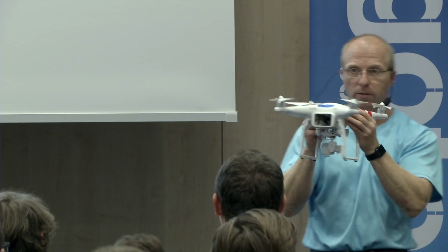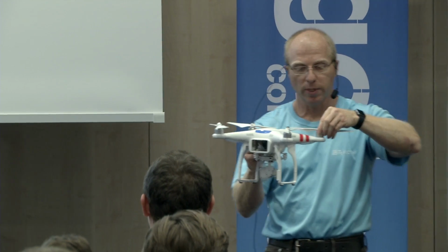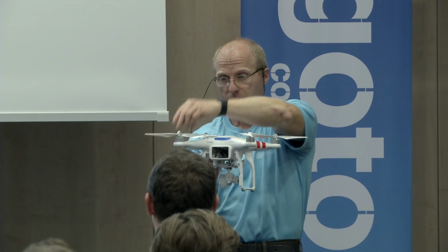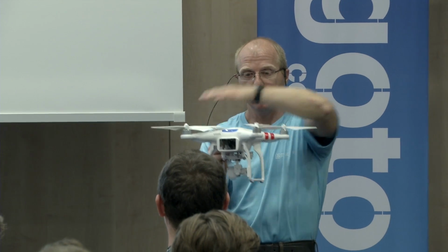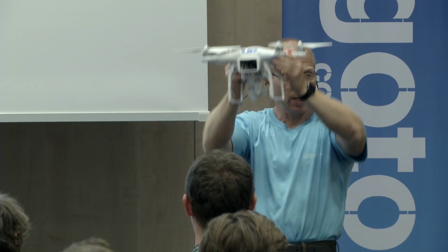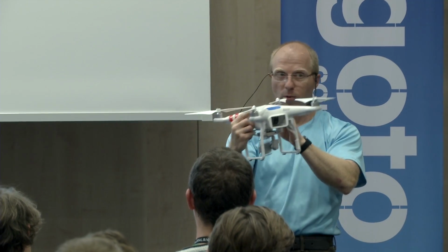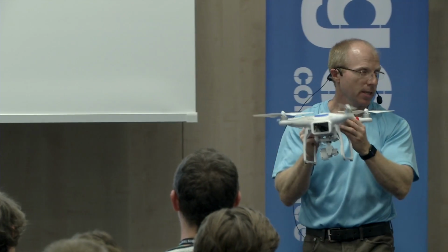What if I wanted to rotate the yawing here? Well, again, I could just increase the speed of the two propellers turning clockwise. Then the thing would start to turn counterclockwise. But at the same time, it would gain altitude, because now I have increased the combined pitch. So again, I have to increase the speed of two of them, and at the same time decrease the speed on the other two. Then it hangs stable and it rotates. So everything is about controlling the speed of the motors here.